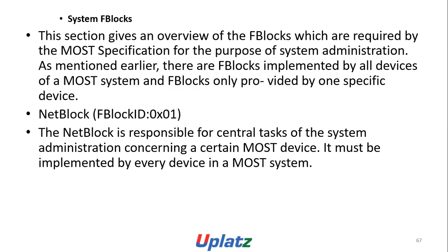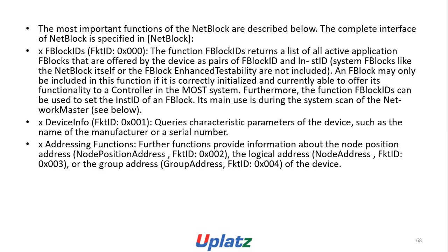NetBlock, FBlock 0x01. NetBlock is responsible for central tasks of the system administration concerning a certain MOST device. It must be implemented by every device in a MOST system. The most important functions of the NetBlock are described below. The complete interface of NetBlock is specified in the NetBlock specification.